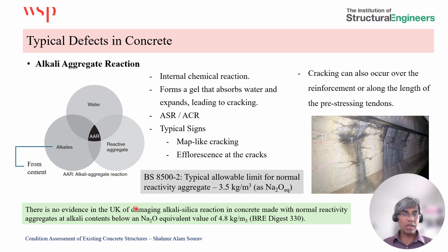I have put this information here just for our knowledge, for information. I've taken this information from BRE Digest 330. There is no evidence in the UK of damaging alkali silica reaction in concrete made with normal reactivity aggregates where the alkali content is below 4.8 kg per meter cube.